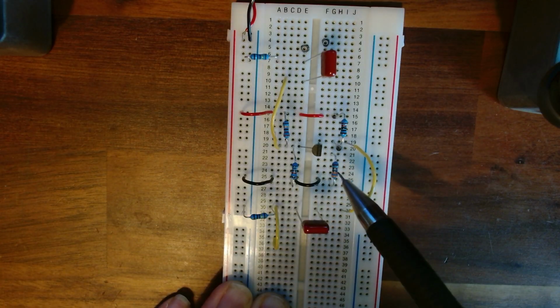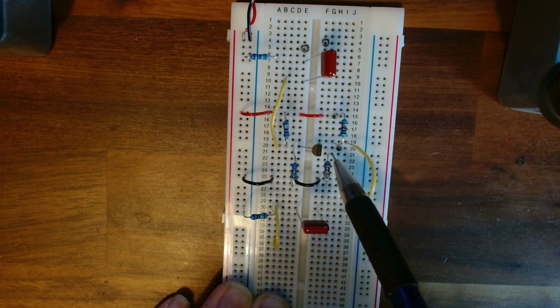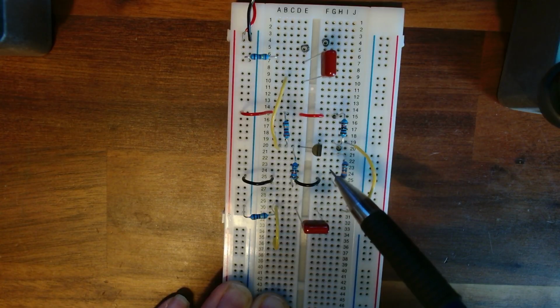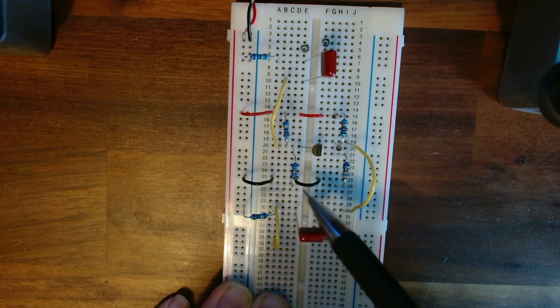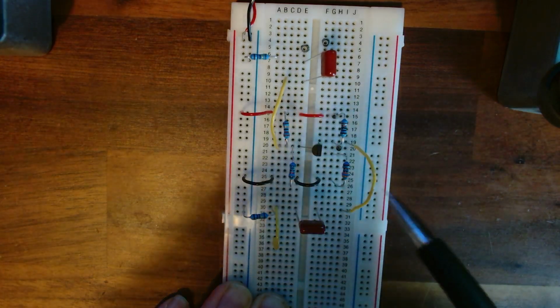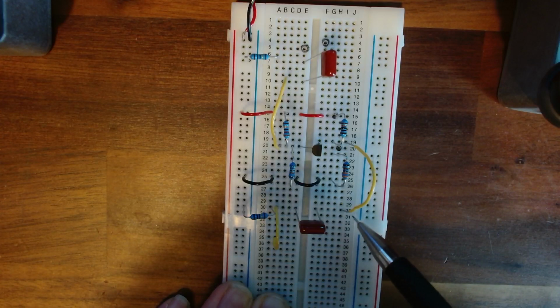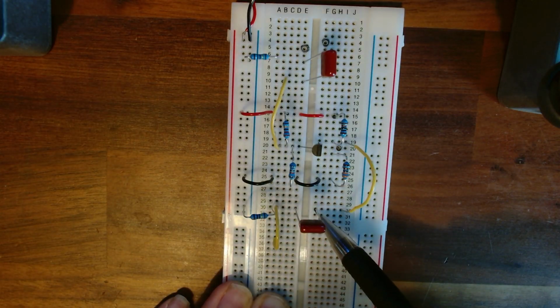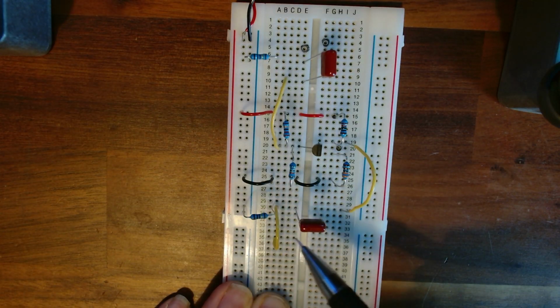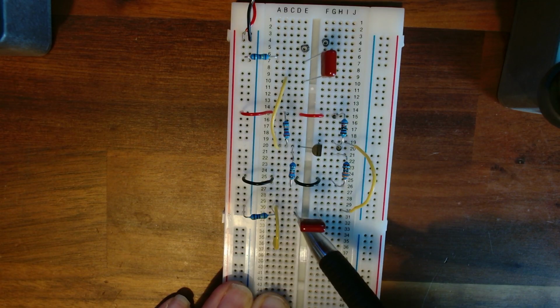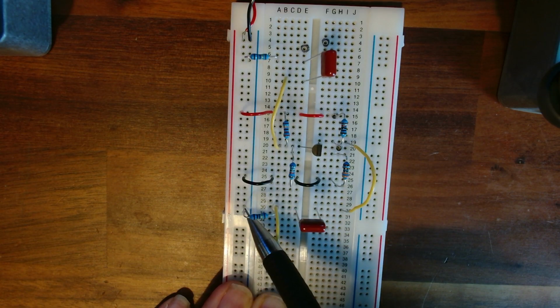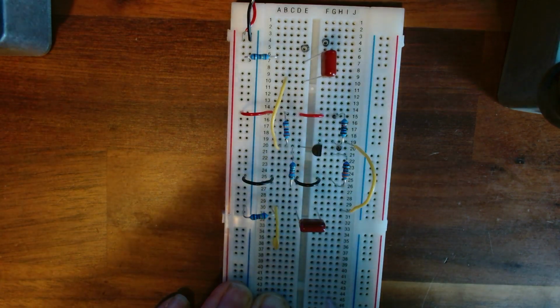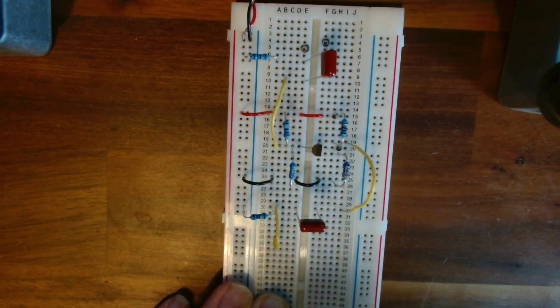And then we're going to take our emitter on line 21. This is our 3.3k, and we're going to take it to ground. I've just jumped this across from the other side the same way. On our yellow line here on pin 30, we're going to go to the input of our capacitor, and still on pin 30, across to our second 1 meg, which is going to ground, the blue side. And then again a third yellow line over here so that we can connect our output later on.